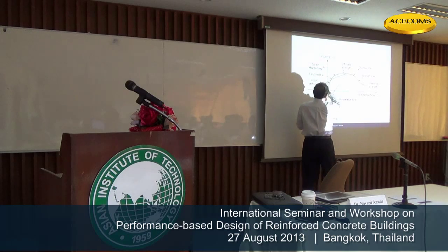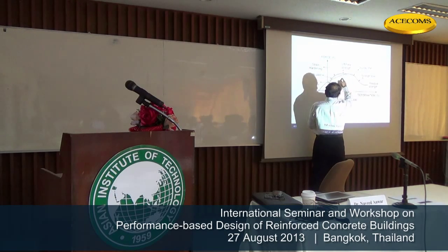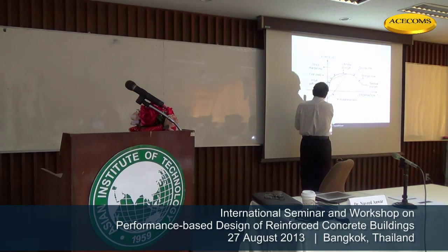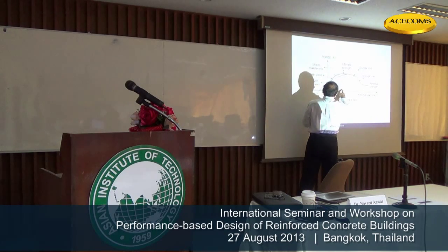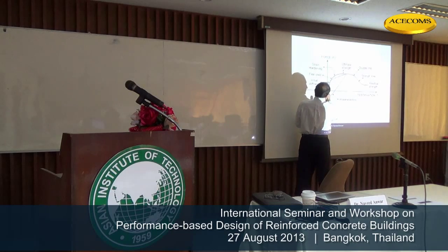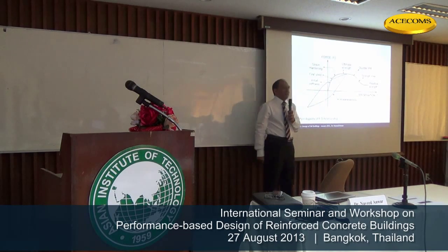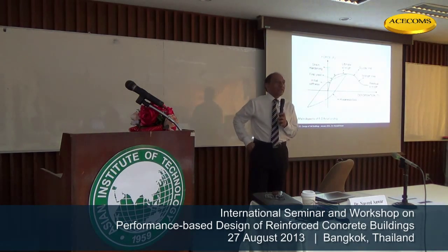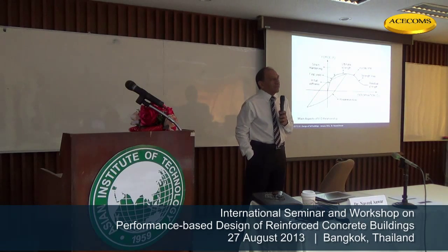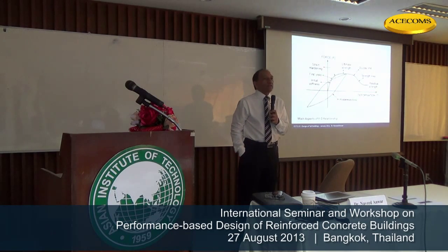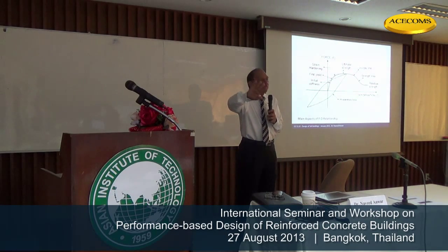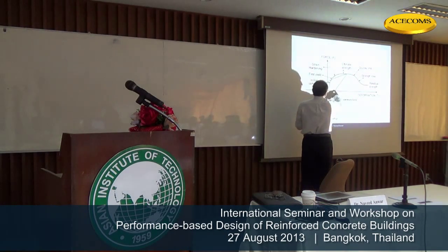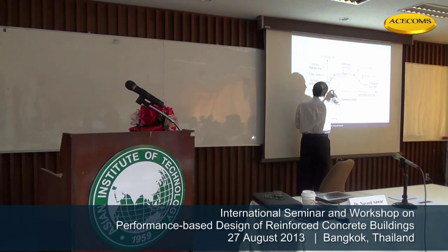However, if you load up to this one and start to unload, it may come here, and if you load it again, it may go here on a different loop. That means it will not come back to this point anymore. So it's not only nonlinear, it is also inelastic. It doesn't return to the origin. It becomes permanently deformed. If you try to unload, it will come back, but when the load is zero, the deformation is still not zero.